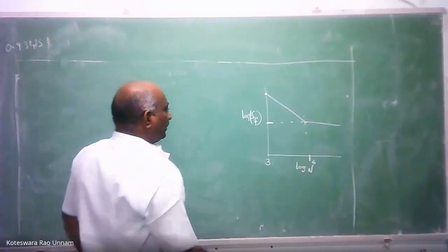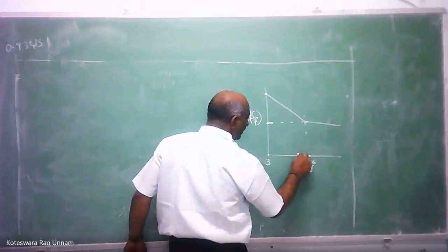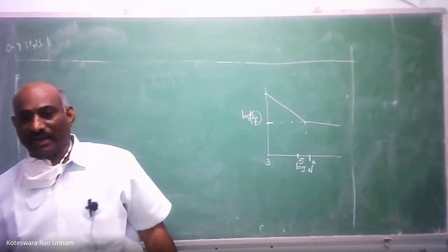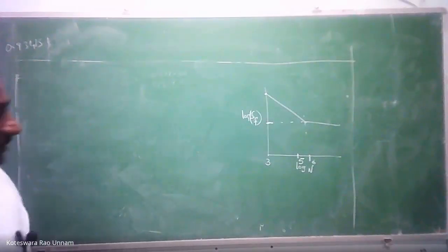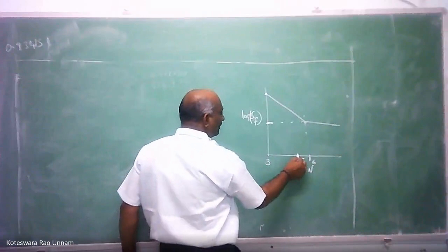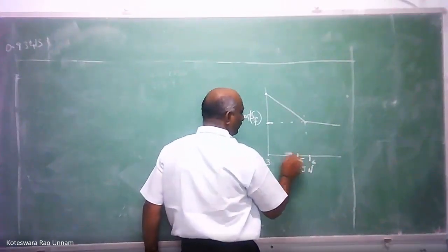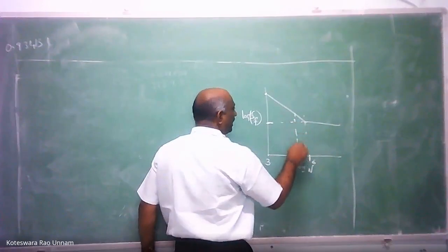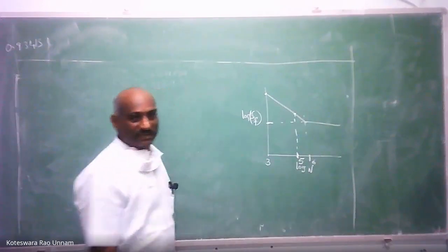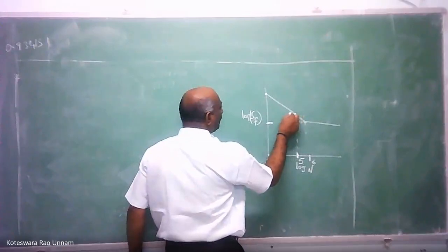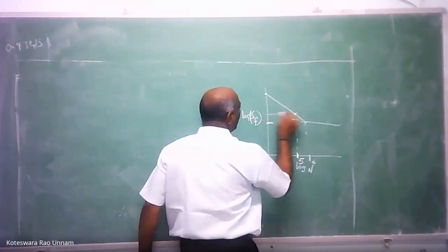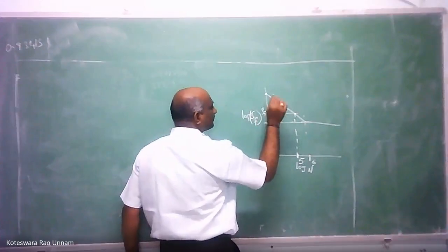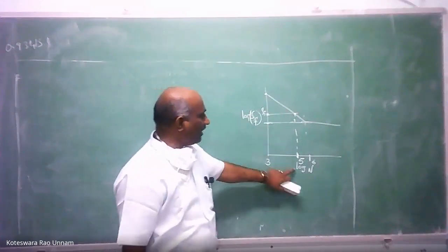Now in the problem itself, it has given the life is 10 power 5 cycles. If I take the log of 10 power 5, I get only 5. So this is my point on the horizontal axis, the life axis. If I extend that onto the failure curve here, I'll get an intersection point. This is your SE, and this is the actual required fatigue strength for the component to have 10 power 5 cycles.